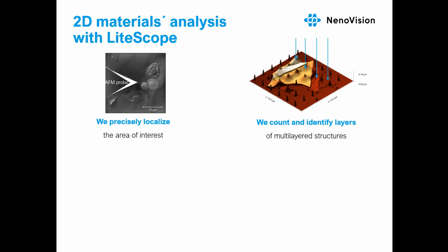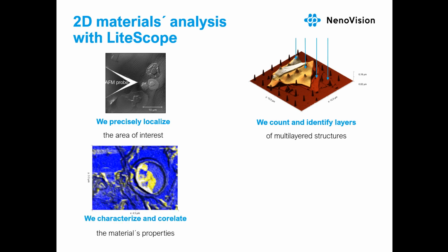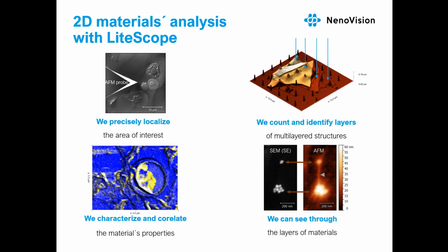Also, the AFM and SEM approach allows for comprehensive sample analysis, including, for instance, material contrast and chemical analysis in combination with materials' mechanical and electrical properties. And lastly, the fact that AFM and SEM rely on completely different imaging strategies enables analysis of heterogeneous materials and structures, where using just one technique wouldn't be sufficient.